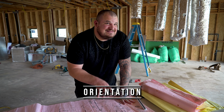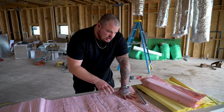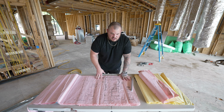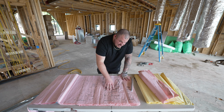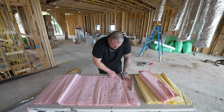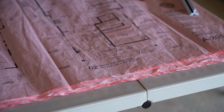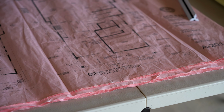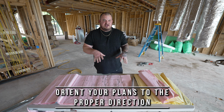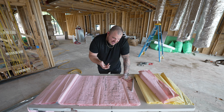Okay, let's talk about orientation. Now this can get a little confusing, especially if you don't have a good spatial brain. You have to imagine when you're looking at these plans that you're facing in the direction that you're looking. So what I always try to do is find what is the front of the house. Here's our front door. Or like on the site plan, you'll see where there's a street. Here's our back stairs. So I know that I'm oriented toward the front of the house. And if you're not really that good at this, just take your plans and stand in the position, orient your plans into the physical orientation that you're looking at. It'll help you wrap your mind around it. The more you look at this stuff, the better spatial recognition you'll have, and you'll be able to look at this in more 3D.